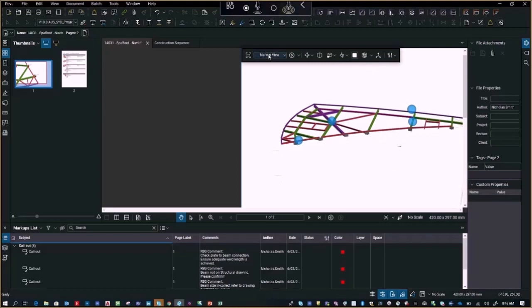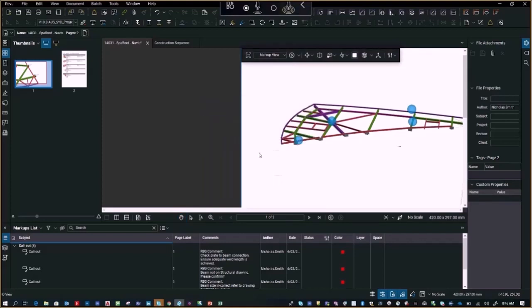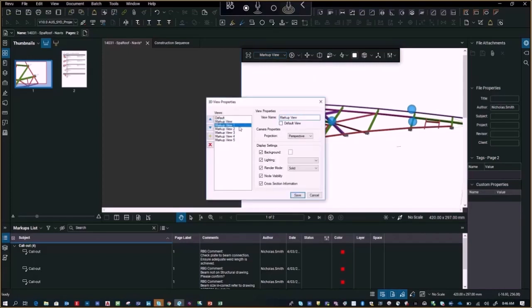So all those views you can obviously rename. You can rename those going to manage view. Now there's no shortcut, and you can't get this window to stay up. So you have to go into this drop down and go manage views. RBG1, RBG2, and so on.